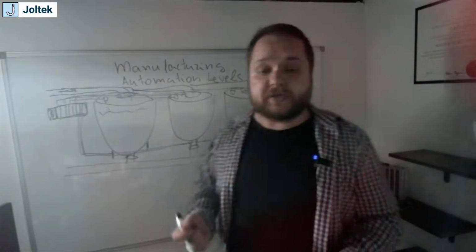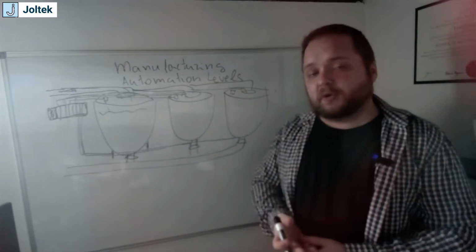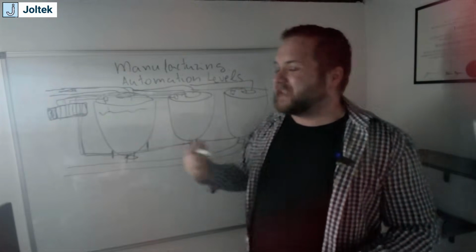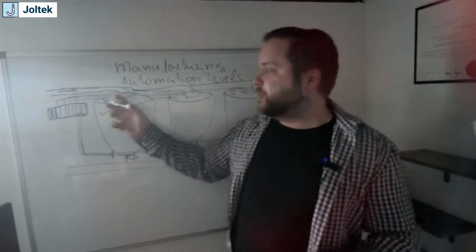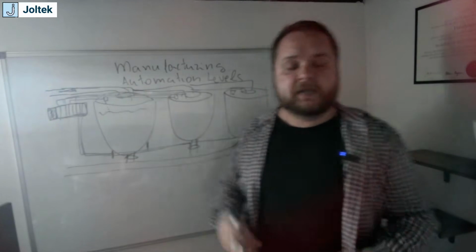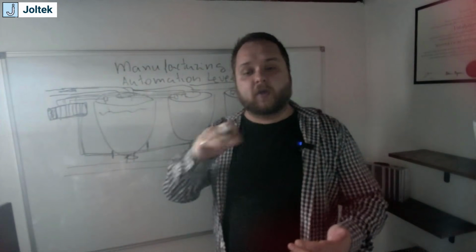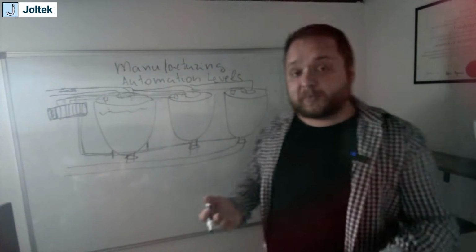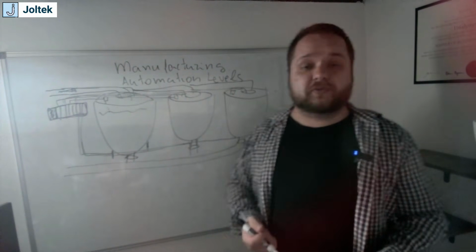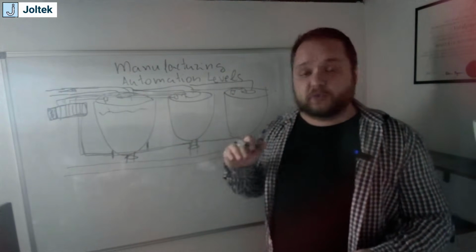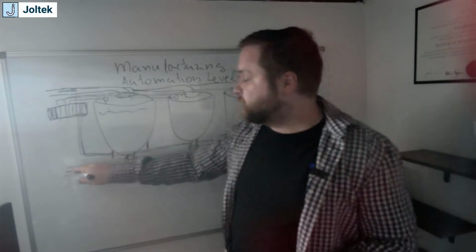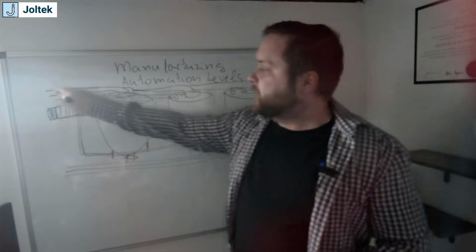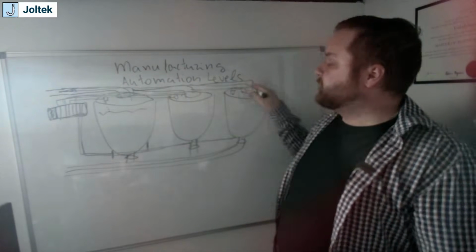So now your IO needs to handle either current or voltage, but it also needs to send out signals, either digital or analog. So for example, if you're only opening and closing those valves, so you're not doing any control when it comes to the position of that valve, which is also possible, then you're only going to need digital signals. But if you're going to do position, obviously analog is going to be required. You also need to run both of these conveyors. And remember that running a conveyor is going to be, again, once through a VFD or a contactor.